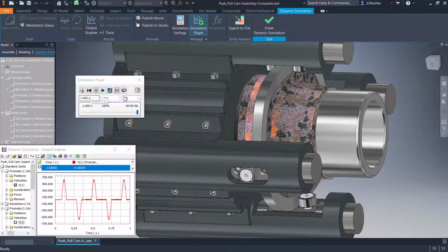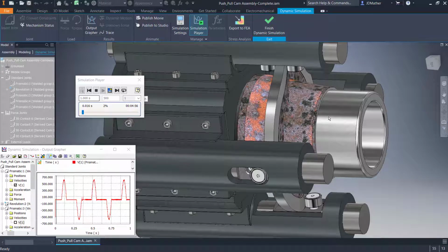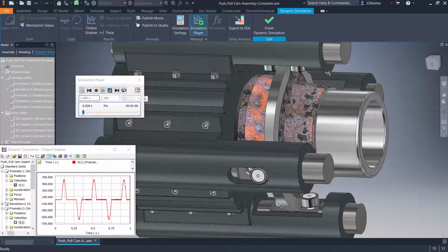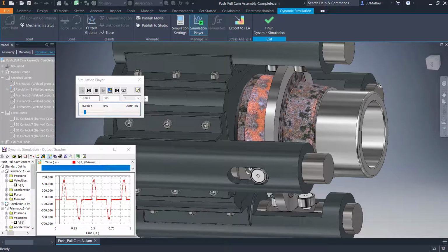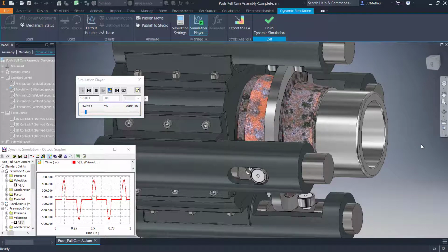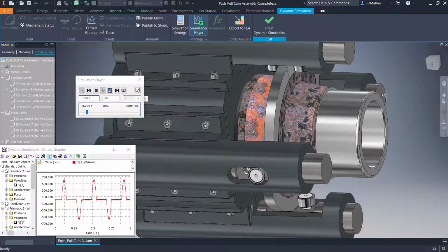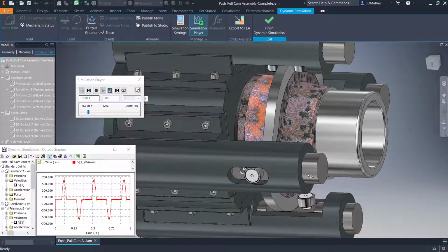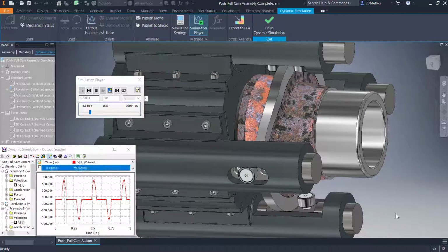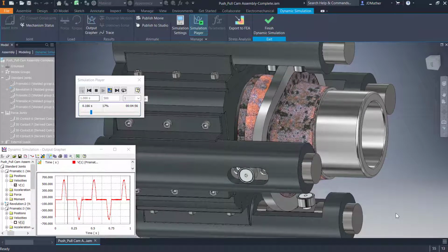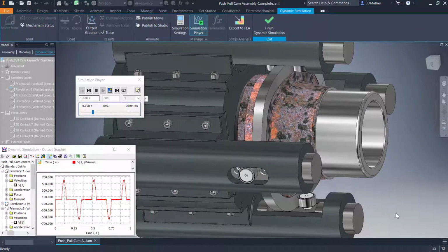Let's slow this down a little bit, and I'll play it again. So we see the cam is rotating, this shaft is lifting, this one is dwelling, this one is dropping, and this one is dwelling. Now this one is dwelling, this one is lifting, this one is dropping, this one is in dwell. So it dwells for 120 degrees, the lift or fall is for 60 degrees. Harmonic motion.